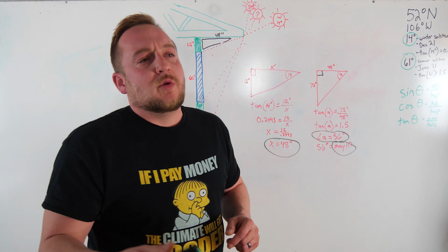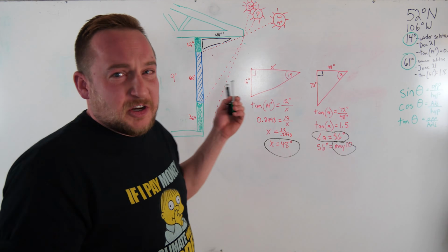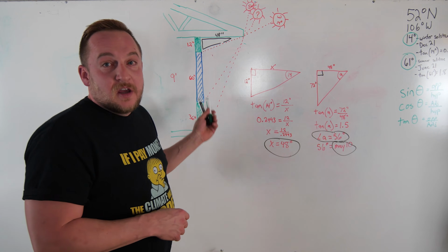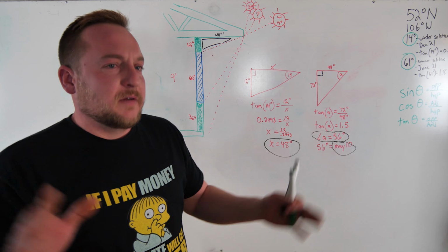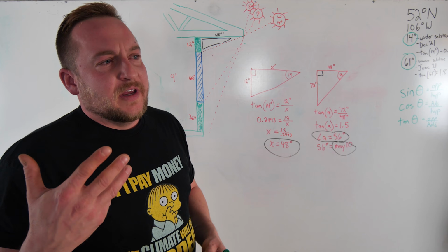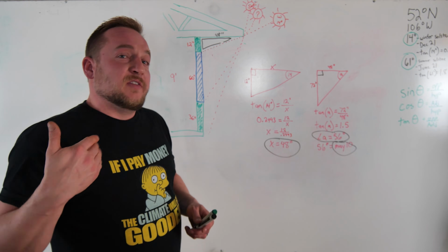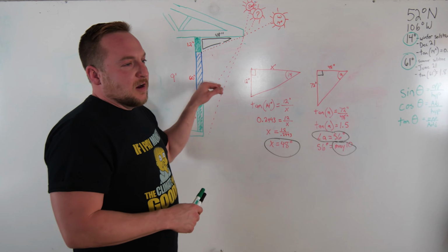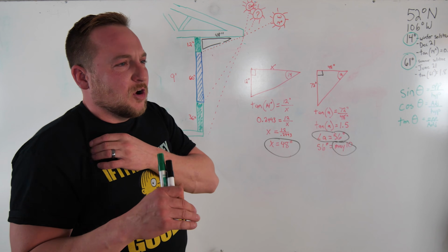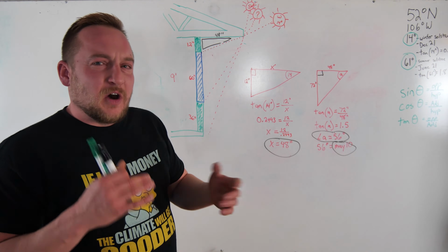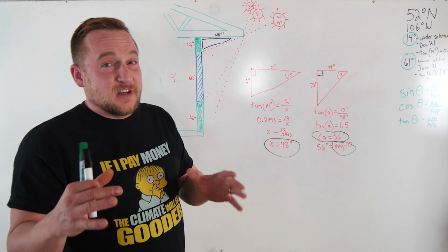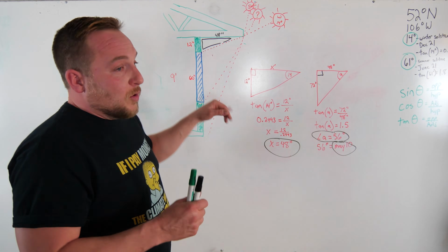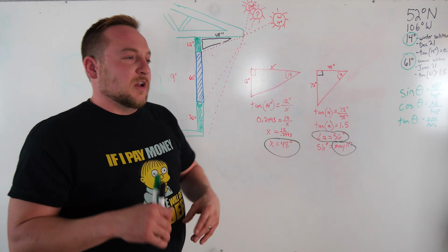Now in a passive solar house, there is actually a percentage of glazing. You don't want full glazing, because that will overheat your house during the day, and then you'll have more heat loss at night. So there's actually a formula. It's called the 7% rule, for the amount of glazing versus square footage on the interior of the building. So you don't want too much glazing, and you don't want too little glazing.